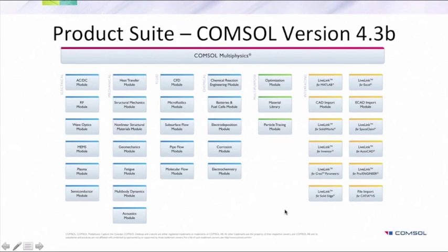There is also a possibility for this in COMSOL, but just to let everybody know, not everything that can be created. There are some limitations. It needs to follow the syntax which is used in COMSOL. For example, if you have some internal variables which can be defined with PDEs or ODEs, then you can create an additional physics where you calculate this variable, and you can calculate strains, for example, in the structural application by use of those variables.